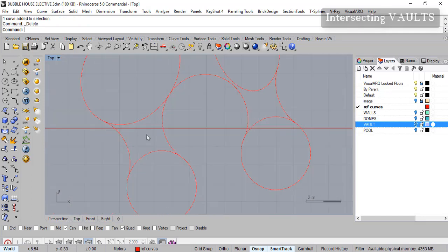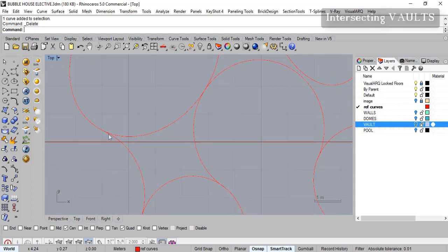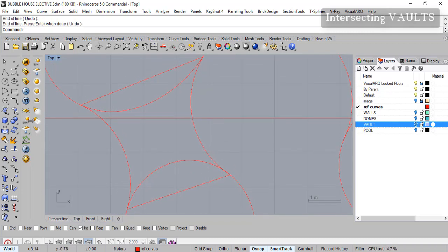So in order for us to exactly draw perpendicular between these two lines, we need to really identify where the intersection lines are, and we'll have to draw a line here. So I'll right click on this, and this time I'll put only the intersection mode on, and just find the intersection here and find the intersection here and draw a line. Again, come back here, find an intersection here and an intersection here, draw a line. And then we'll draw one more line between the midpoint of this and the midpoint of this. So we'll have to put the midpoint on now and just draw a line here.